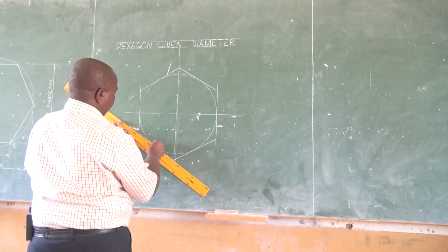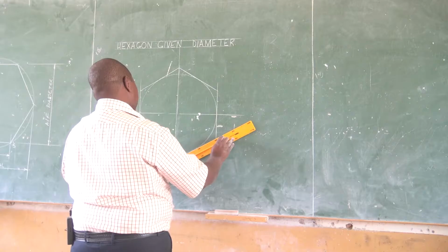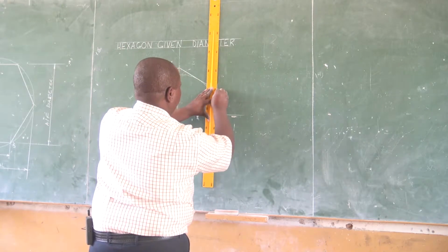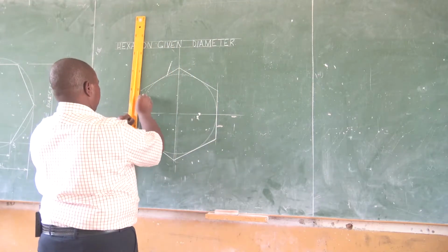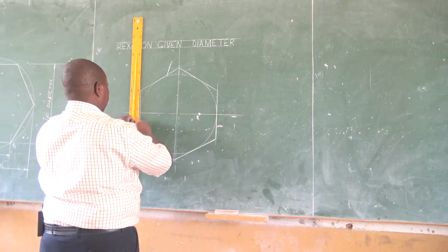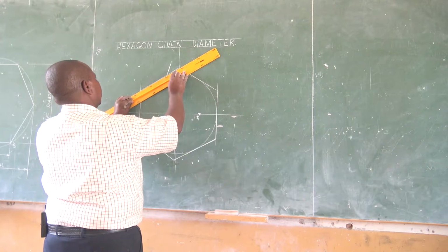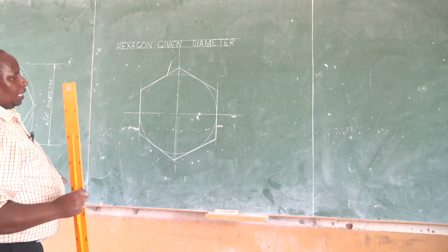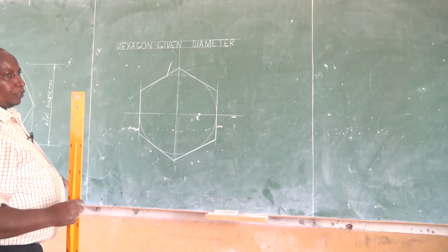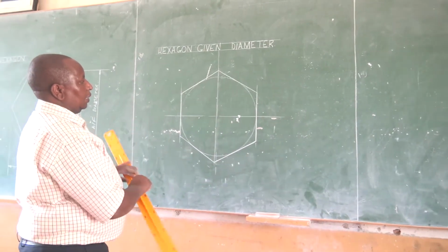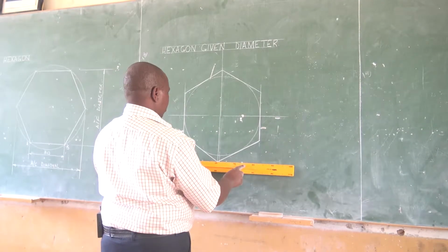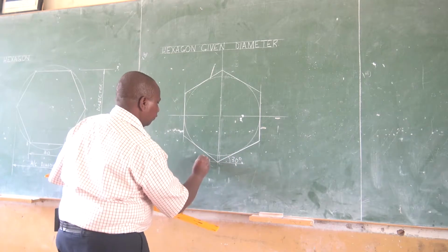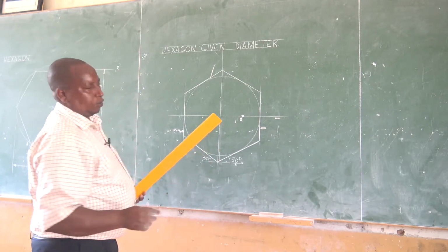the polygon, which again we agreed that the diameter means the diameter also of an in circle. So you proceed to outline the completed hexagon. Once again, when we are given the diameter, bisect the diameter, draw the circle with half of the diameter being the radius, and proceed to draw tangents at an angle of 30 degrees below here, and also on the other side at vertical, completely vertical, and at 30 degrees at this one. So if this angle is 30 degrees on either side of the true vertical line, then we complete that hexagon.